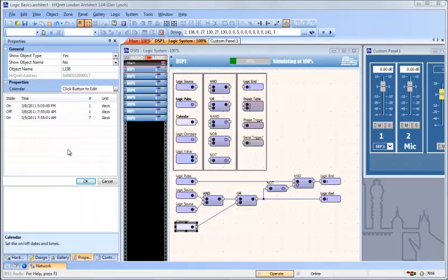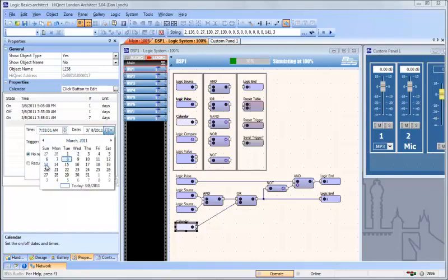Now, this is going to overlap with the 5:05 p.m. trigger, because at 5:05 p.m., the trigger will be told to turn on, but it's already going to be on from the morning trigger. That's no big deal. It won't bother anything. It'll work just fine. The calendar object does not toggle when the trigger time happens. Instead, it sets itself on or off based on the way you programmed it. I can do the same thing for 7:55:01 a.m. starting on Sunday.